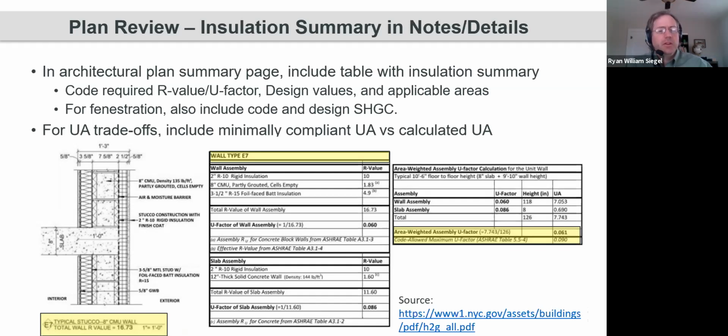That is something you may look at as part of your design, asking whether you can make a trade that might be better performing. If we improve the exterior insulation up to R15, that leaves the cavity available for running electrical and data cables and other things, which would otherwise have to be insulated around and may increase the difficulty of that insulation.